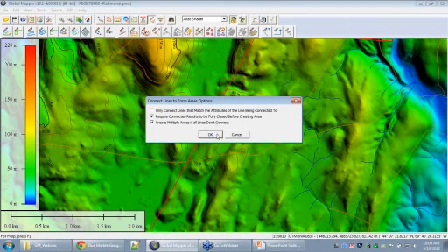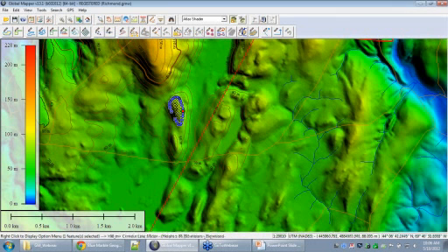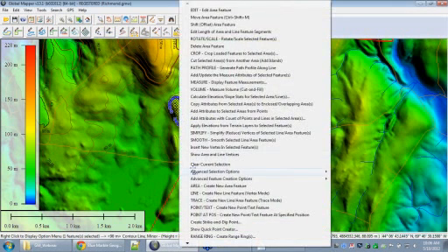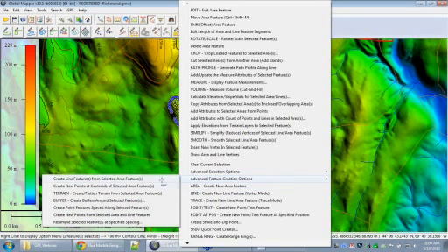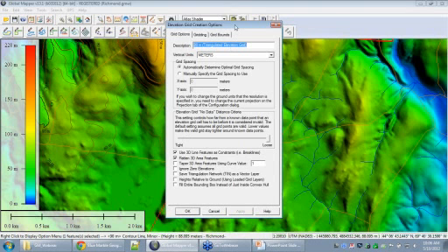So we're going to create an area feature from that line feature, and there's a few options for that area creation if we're going to be combining multiple lines into an area. And so we create that new area feature. So I've got my 80-meter level there as the elevation for that feature. So there's my new area feature. Now if I right-click on that under my advanced feature creation options, I'm going to have the option to flatten out the terrain in that area.